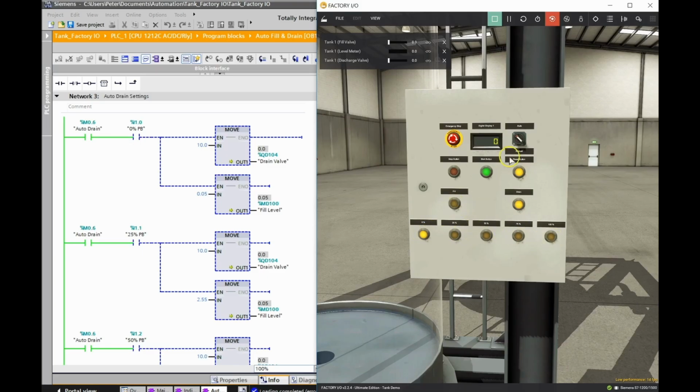And now in our auto mode, in filling the tank, we can now press these push buttons and bring them up to the appropriate levels where they stop exactly at the 25, 50, 75%, or 100. Then we can go into the drain and drain it out to 75, 50, 25%, and 0% as well. There are some things that are missing in this program though. For one, in this portion on my auto mode, I haven't made use of the e-stop.